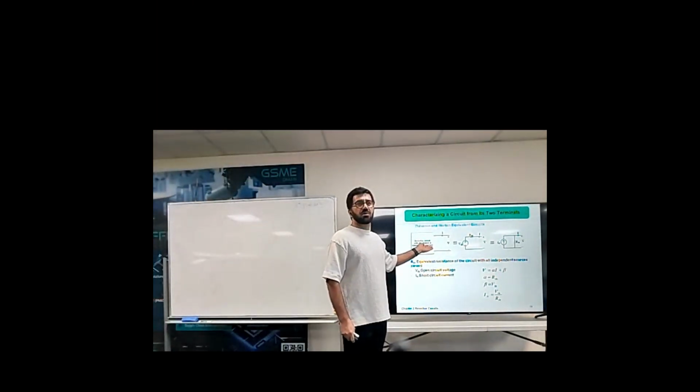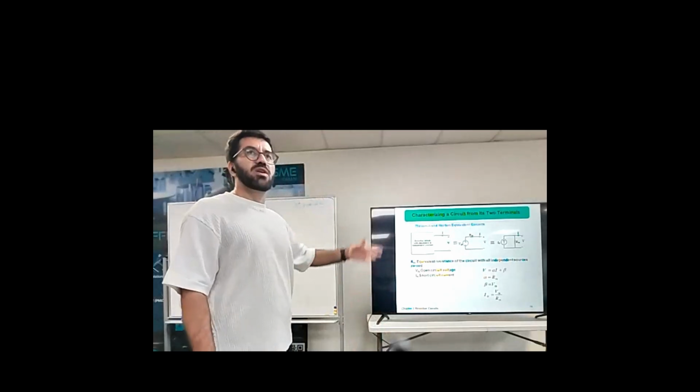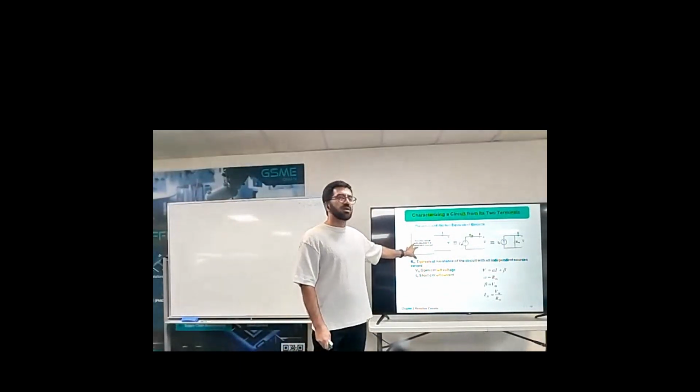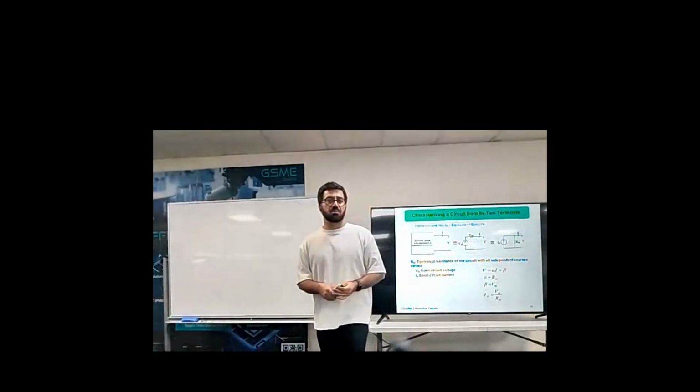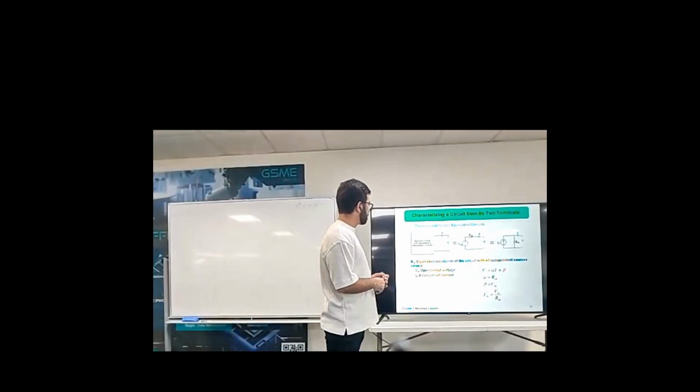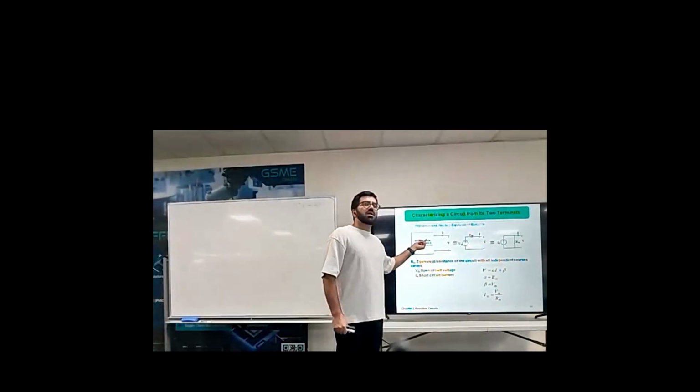Last session, we saw if we have a resistive circuit with dependent and independent sources, no matter how complicated this circuit, bunch of resistors, maybe 100, bunch of dependent and independent sources, no matter how many branches are inside, we can simplify that complicated circuit only with one voltage source and one resistor. The only condition is they should be linear. Yeah, resistors should be linear. Or we can replace these complicated circuits with Norton equivalent. One current source parallel with one resistor.